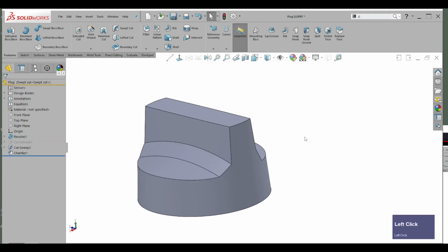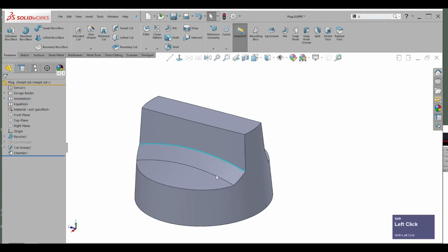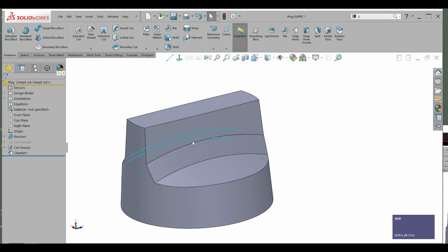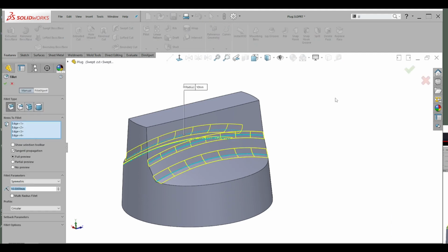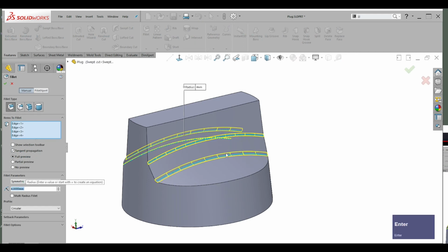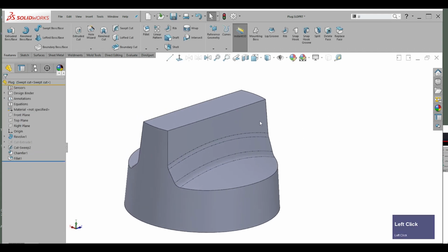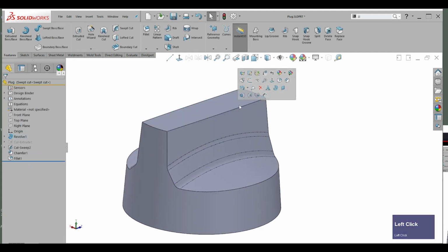Go. Right, and then I think I also selected these. I'm holding the shift button down, by the way. I think you can see in this little block what I'm doing. So if you don't know what it is I'm doing, just look in this block and you'll see. And then right click, I'm going to give that a fillet of 3, maybe 4 as well, maybe 6. It looks better. Right. And then I'm going to put in smaller dimensions on these two lines, right click, fillet, make this 2.